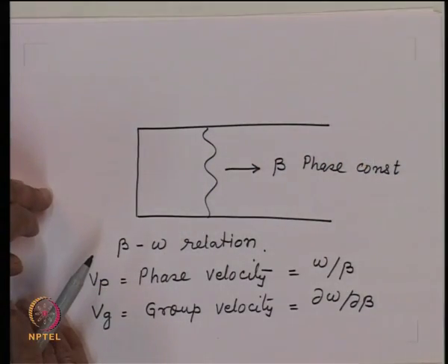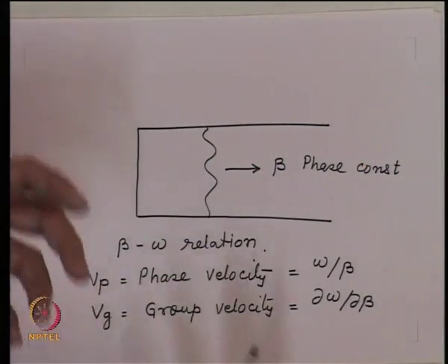And once we get a group velocity, then we can ask a question that if a light pulse was launched inside the optical fiber, how different frequency components will travel, and because of the variation in the group velocity, how the pulse is going to get deformed inside the optical fiber. So, this analysis of wave model is essential in finding out quantitatively the variation in the velocity of a pulse inside the optical fiber, which gives you information about the distortion of the signal on the optical fiber.